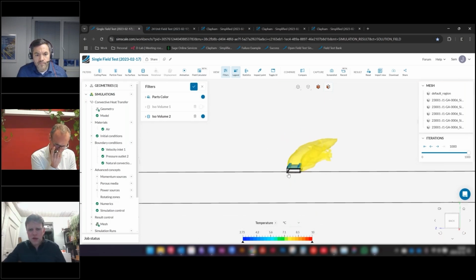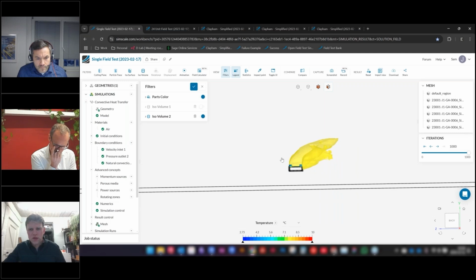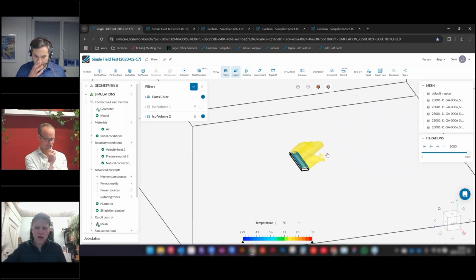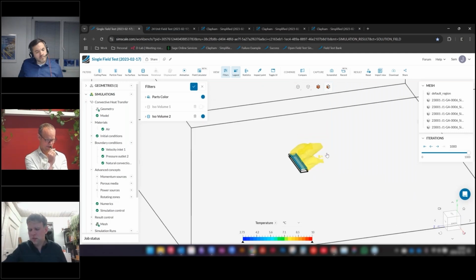I won't go into every piece of detail here, but one of the things that we see as a positive outcome is that we're seeing good air dispersion as the fans are jetting the colder air upwards. We're seeing that get carried away with the ambient air and also mixing. So that means we've most likely mitigated the risk of recirculation and contamination of the cold air back into the intake. We do this for our own sanity, to make sure that we're expecting the correct outcomes when we start to put this into the built environment.